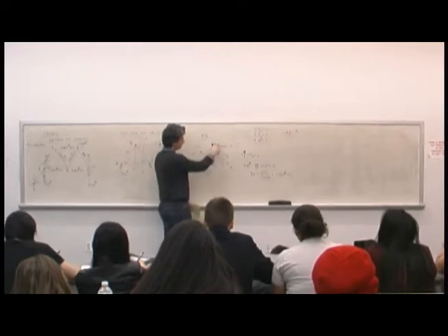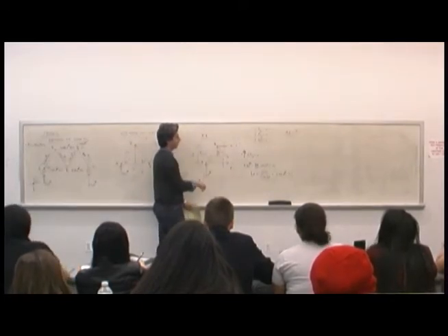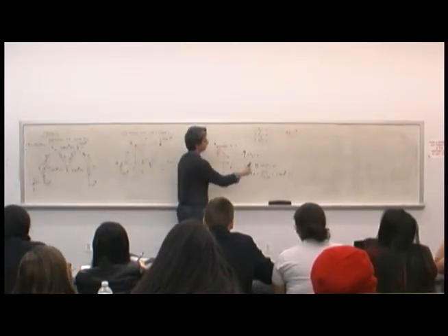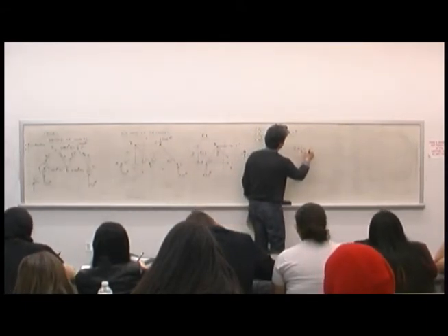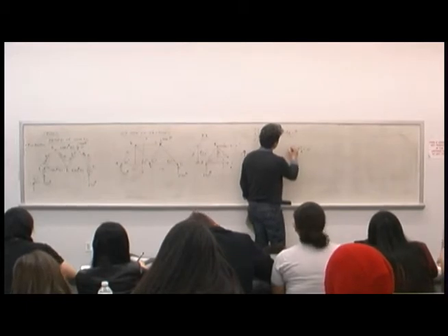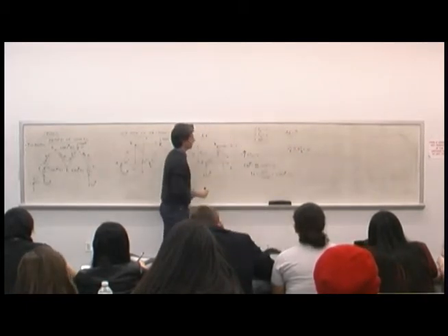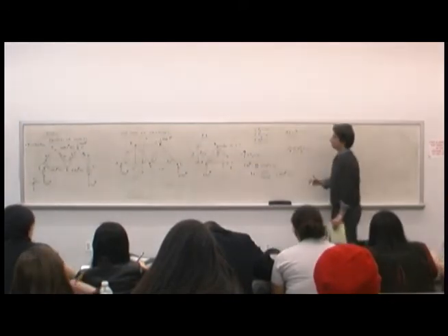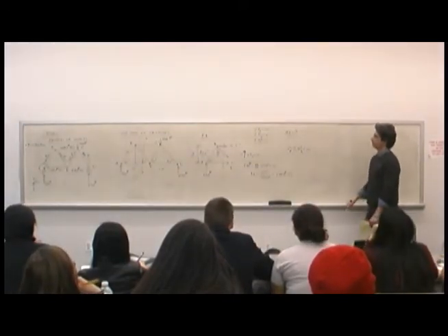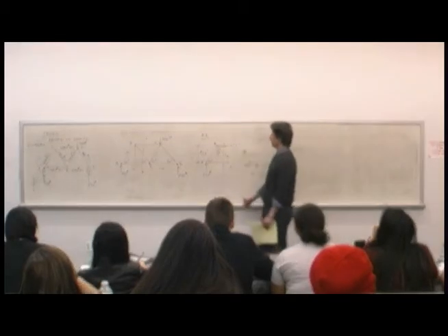So, taking the moment around somewhere on this structure to my advantage, I'm trying to put myself somewhere on this structure to eliminate unknowns. So I put myself at B. If I sum the moments about B, I know they have to be equal to 0. I'm going to say everything going clockwise is positive. So what happens? What's the 250? Which way is the 250 spinning around B?